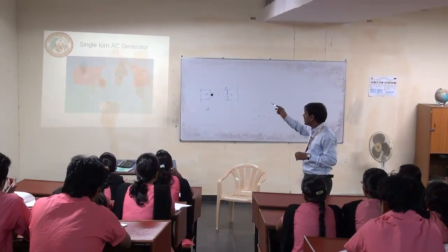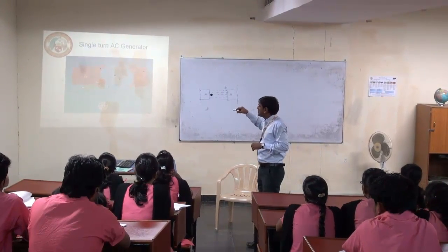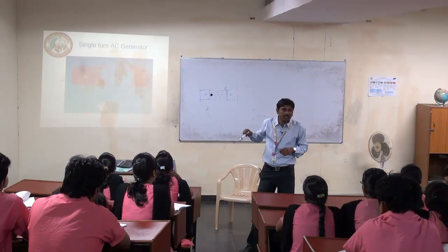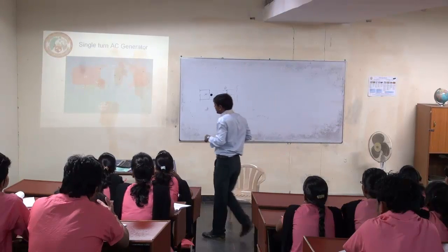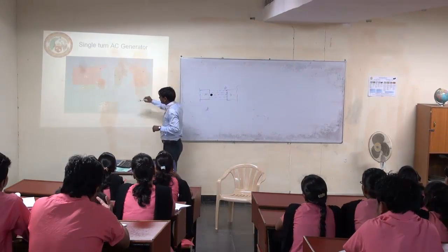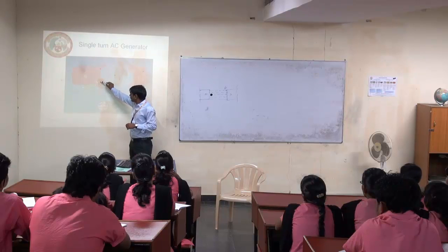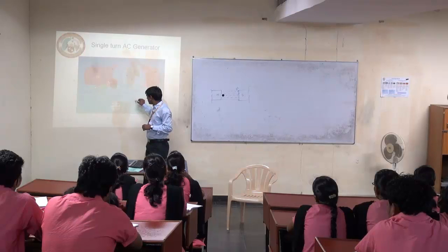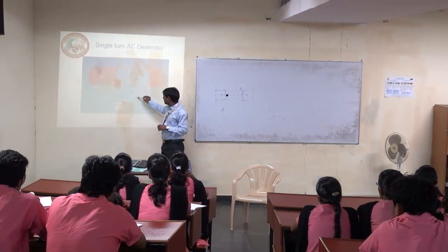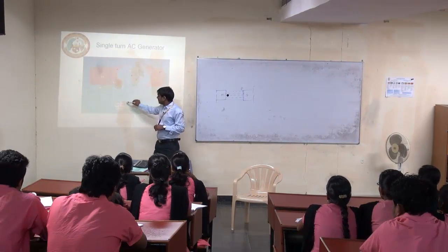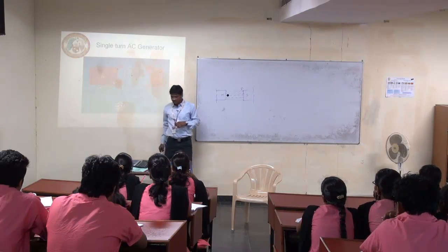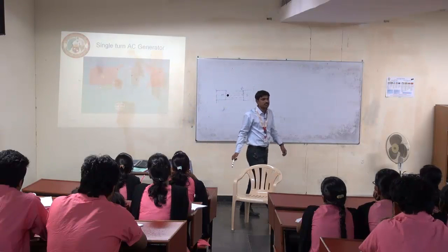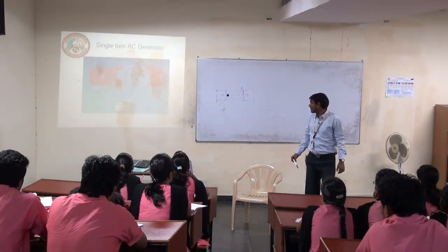When you rotate the single turn coil, there is a dφ/dt and an EMF will be induced in the conductor. That induced EMF will flow to the slip rings, through the brushes, and to the load resistance, which will consume the energy and close the circuit. This is the galvanometer to measure the deflection of the induced EMF.